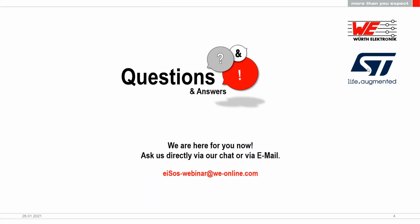Okay, thank you. Then let's go on. Next question. Can the ST USB4500L and ST USB4500 be used in USB data application? So the answer is yes, of course. A USB data controller can be implemented in parallel of the USB PD controller. And it can be scaled to either USB2, USB 3, or soon USB 4.